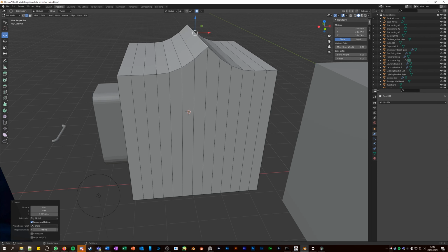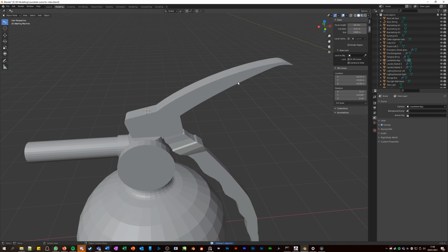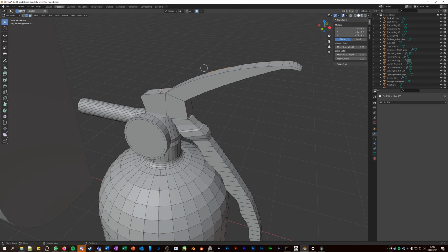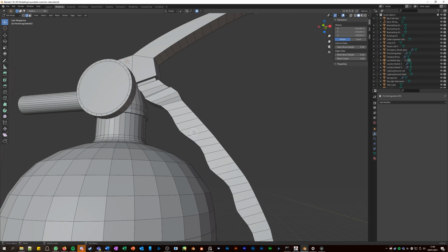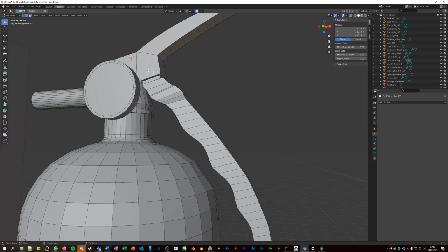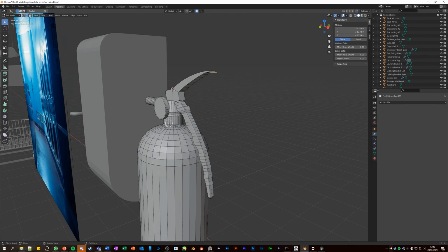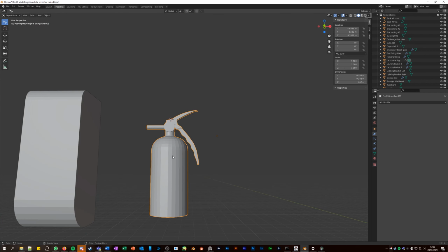It kind of allows you to move the lines next to it, not as much as the main one you're trying to move. So I chose smooth and rounded it off. That's how I got this rounded top edge. And I pulled one of these corners up, pulled one of those up, and just with proportional editing, pulled this down. And similar here, I did the same thing, extruded the face out diagonally, and then rounded it off with proportional editing, just what seemed right. Extruded some faces to add some width there, and whatnot. Just kept adding to it.